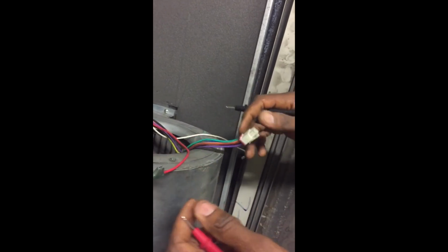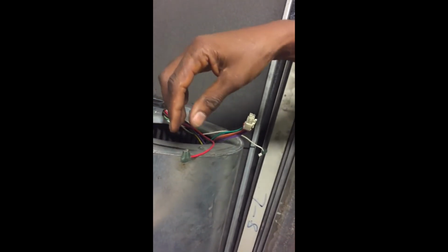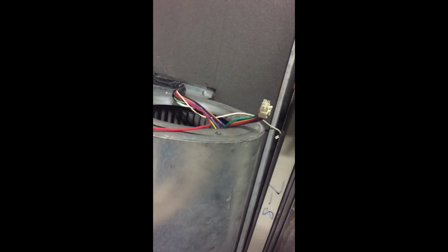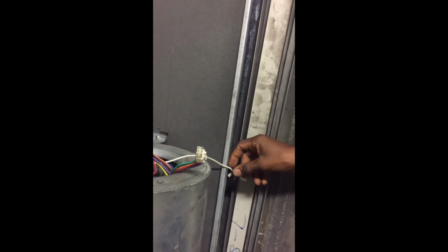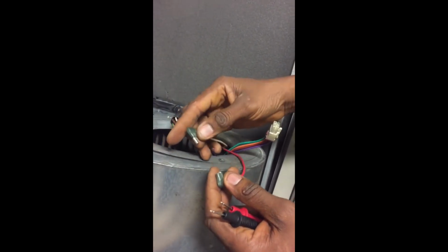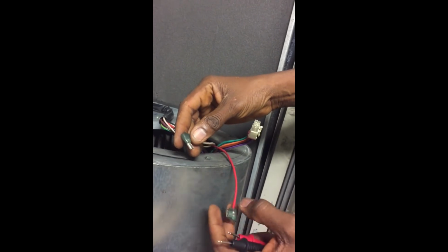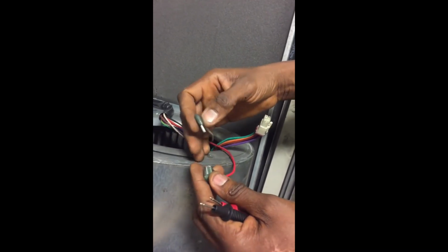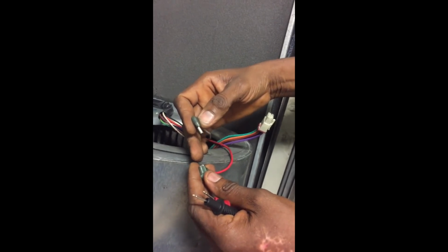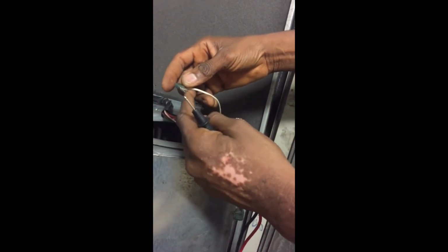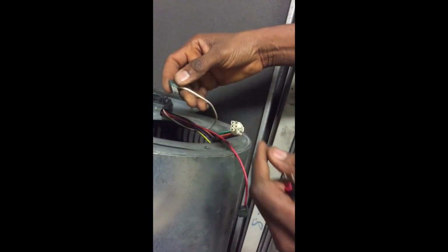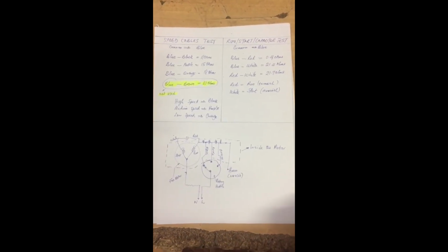So having said that, we have confirmed that internally there's a connection between supply and the run terminal. We will now establish if there is a connection by the time we put our capacitor between these two. We are now going to confirm that one end of the capacitor, because this is one end of the capacitor, is, by the time there is supply on this, provided with the power supply required for one terminal of the capacitor, and the other terminal of the capacitor goes to the start, which is here. So this is the result of the tests that were done.